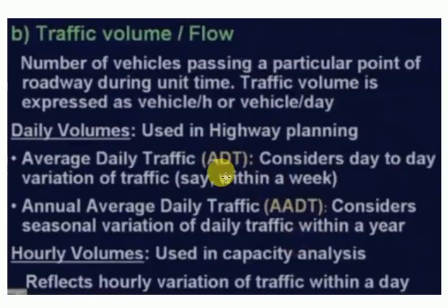Then another is the ADT, that is the average daily traffic. So it is an average 24-hour traffic volume at a given location for some time period of less than a year. It may be measured for 6 months, a month or a week, or it can be say 2 days. So it is a valid number for the period over which it was measured. For that case, no yearly data needs to be considered.